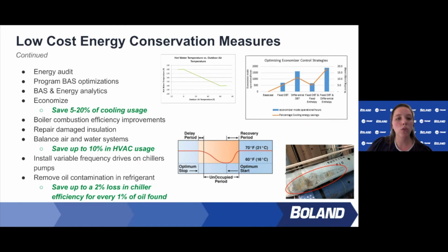This looks past the operational gaps, like a schedule, and helps you find inefficiencies like an outdoor air sensor that's not calibrated correctly, so you can't enable your economizer, and now you're running mechanical cooling when you could really just use the outdoor air and economize. These inefficiencies are alerted in the system, and it helps make your building run more efficiently.